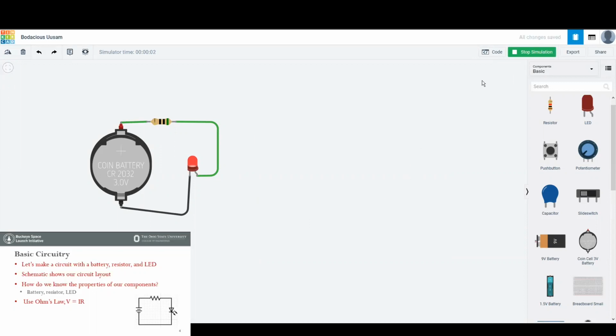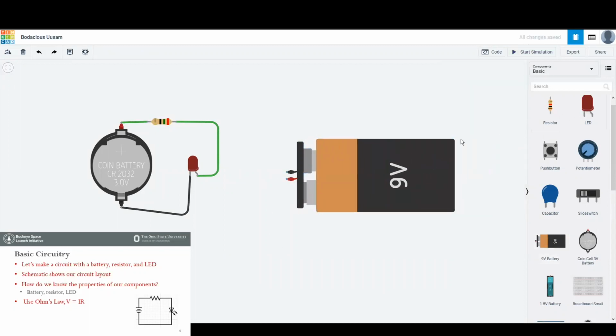It works, right? Let's stop it and let's cut this in half. Let's cut this to 25 ohms. Oh, I said 35. Let's do 25. There we go. See the band's changed again. Let's run it. There we go. We're getting too much current through our LED. If we actually go with too much current through it, take a 9-volt battery, very quickly hook it up, and run it, you actually blow it up. See, we're almost pulling 1 whole amp through that LED. That's bad. It will break it.